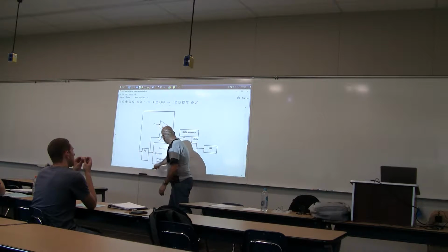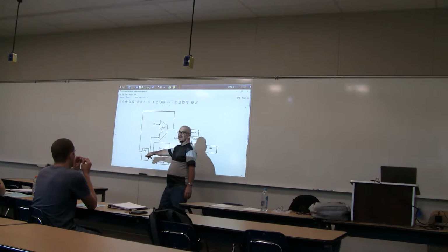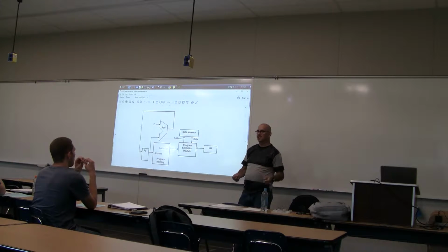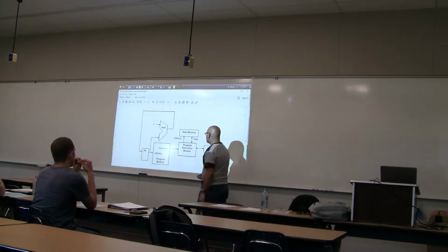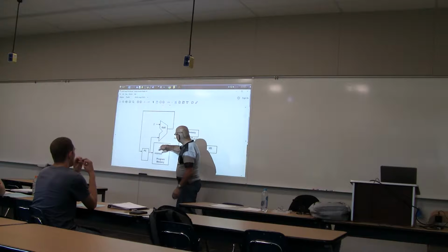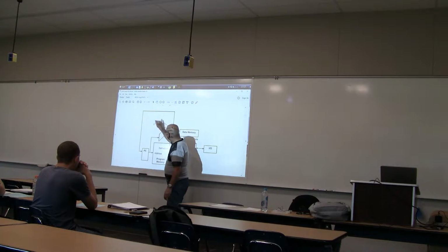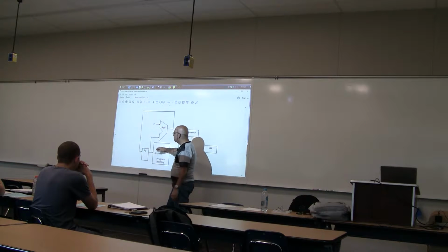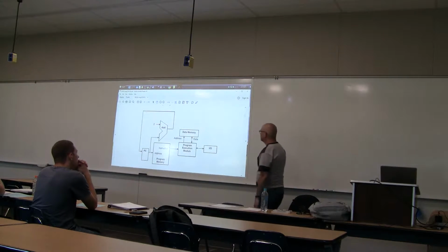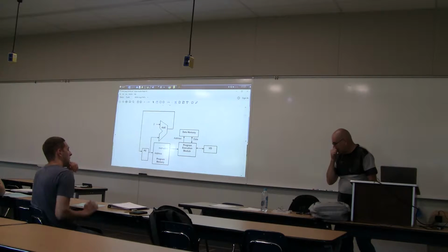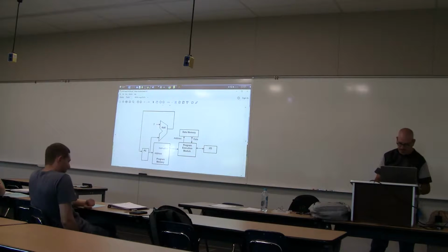And this memory is addressed by something called a program counter. The program counter starts off at 0, and it basically says, where is the next instruction I want to execute? So the program counter says, give me instruction 0, and then the program counter increments actually by 2, and instructions are stored at every other location in here, so 0, 2, 4, 6. So the next time that we get an instruction, the program counter will be 2, it'll read that instruction from memory, and so on. That's a very high-level view of what's going on inside the system.